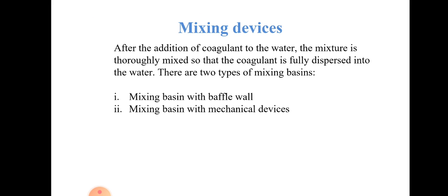Another method is by diffusing compressed air into the mixing basins from the bottom. In this method, the raw water fed with the coagulant will be agitated by this compressed air that is diffused from the bottom of the mixing basins.